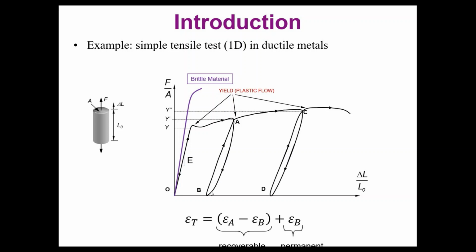When you discharge the loads on your sample and you have reached this level of stresses, the discharge will be more or less parallel to the initial straight line you have in the elastic regime. And when you recharge, you will follow again more or less a parallel line to the initial line of the linear elastic regime. And now your material will have recovered this linear elastic behavior, but until it reaches again a point where there is a sudden change and the material becomes plastic again.